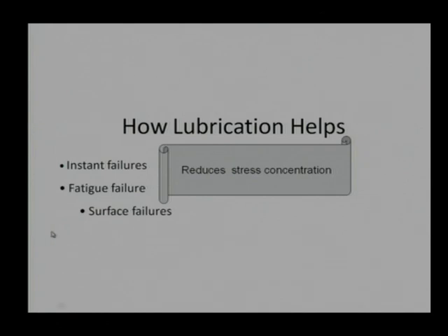In the last lecture, we studied the cam failure mechanism, or cam failure analysis, where surface failure, surface fatigue was emphasized. If we provide a lubricant, that surface fatigue failure will reduce. It was also mentioned that if we provide a lubricant, the coefficient of friction will reduce, sliding will reduce, and that will reduce the force required in the tangential direction. If the force required in the tangential direction is reduced, fatigue failure will reduce. Or we say that life will be slightly higher, or maybe greatly higher, depending on the lubrication mechanism which we are providing.